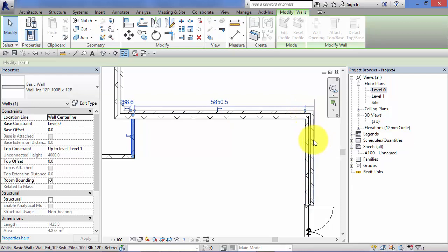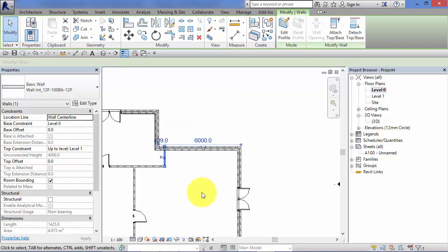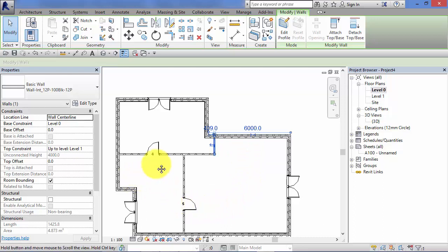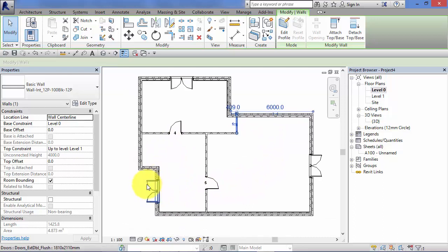and you can see Revit is offering me various positions to re-reference. So if I let go there on the external wall, let's do that again, and let go, you can now see that that temporary dimension measures to the external wall, and now I can click in the value and say, for example, I want that to be 6 meters away, and the wall moves accordingly.